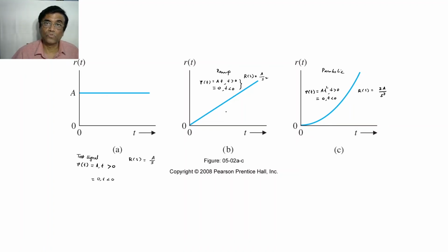Here also a ramp function can be used for testing. So this is, you see, if this is an underdamped system, then this is called the transient response, and then as soon as it becomes like this, it is called the steady state response of the system, because you have an external excitation with a step function.